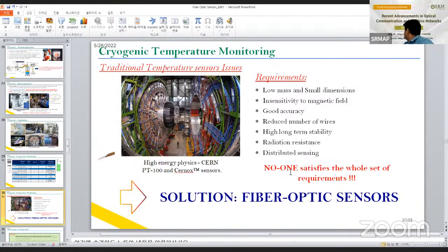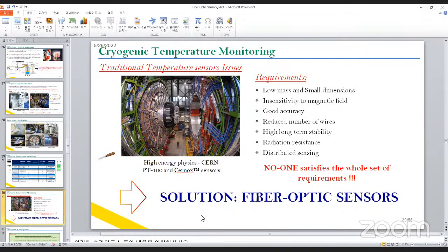Dr. Sampath, I have a question. What are the limitations of this type of optical sensor? Is there any limitation? The limitation is cost-wise; it is very expensive. That is a major one, and the setup is also very expensive compared to a normal sensor. One FBG sensor costs almost $70, whereas for $70 you can get almost 30 meters of thermocouple cable and do the temperature sensing.